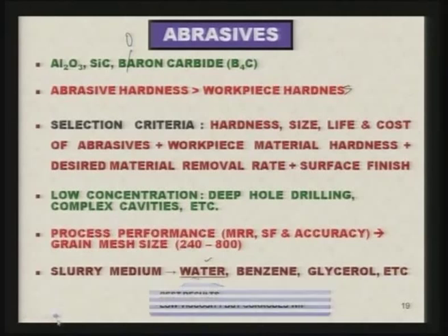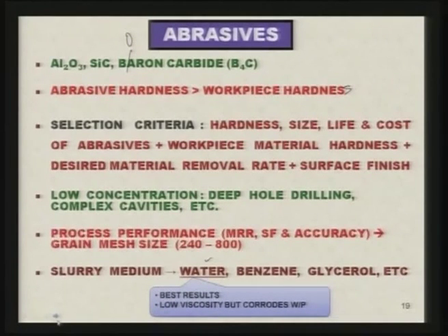If it has high viscosity, then it may not be able to reach those fine cavities or fine details on the machined component. Water gives the best results because of low viscosity, but the problem with water as carrier medium is that it corrodes the workpiece. So, one has to take this also into consideration.